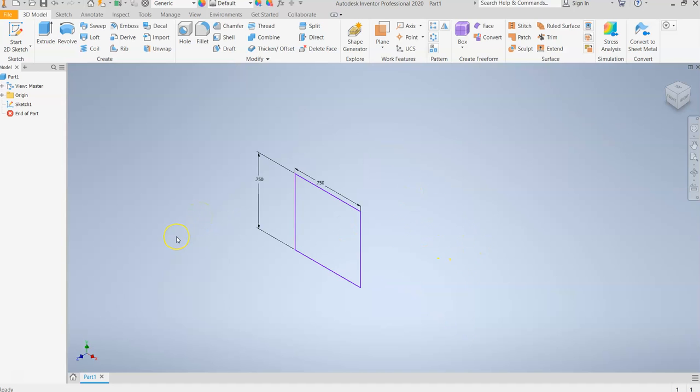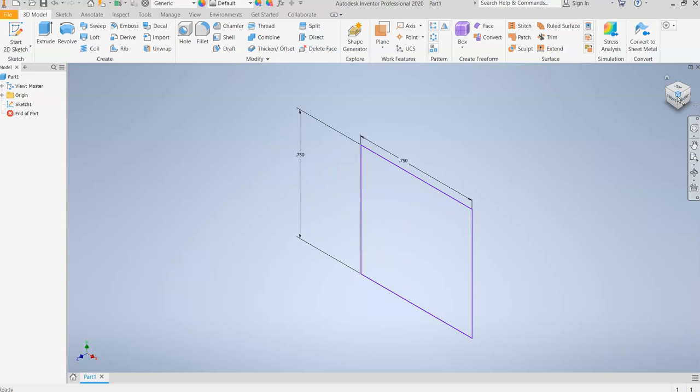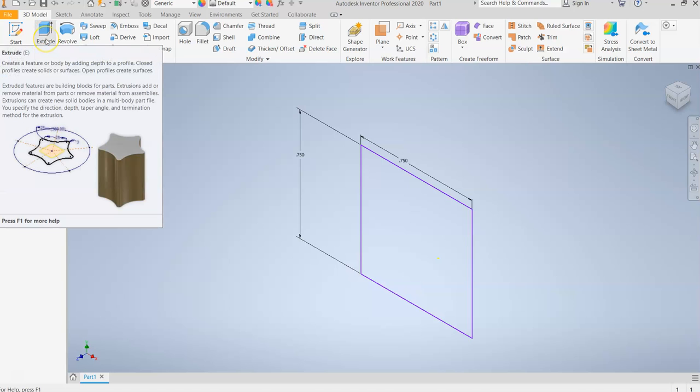I like isometric view when you do extrusions, when we turn it from a 2D sketch into a 3D model. Having it in isometric view is best. So make sure we've clicked on the corner, make sure it's set into isometric view, and then we click the button here, extrude. Now, when I click extrude, the computer is going to use its intelligence, and it's going to predict what you want to do. It's going to assume that because you created a square, you now want to extrude that square into a box. So we're going to click extrude.